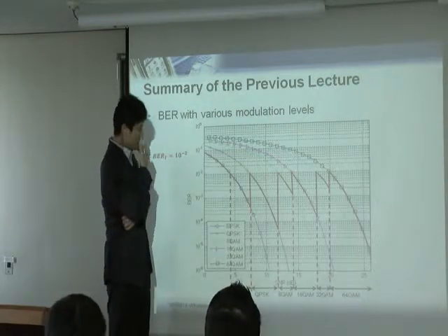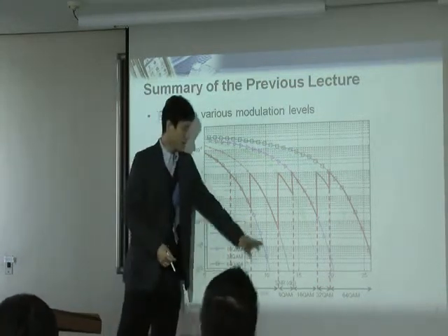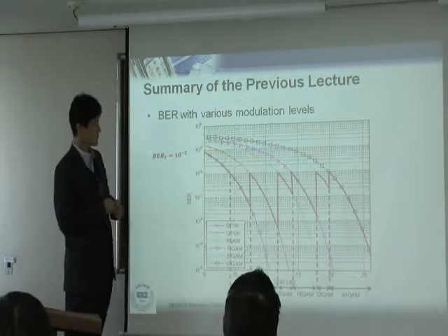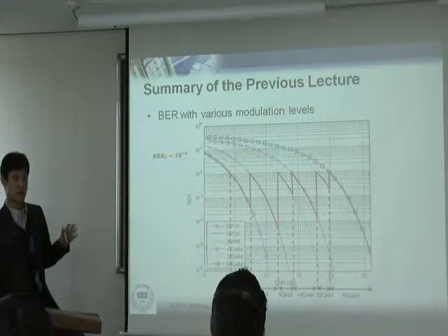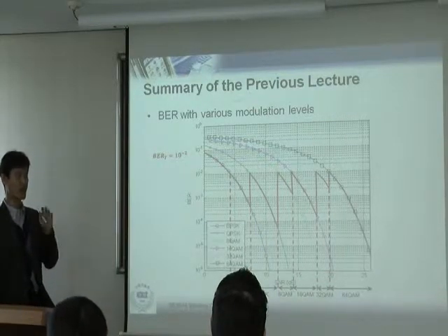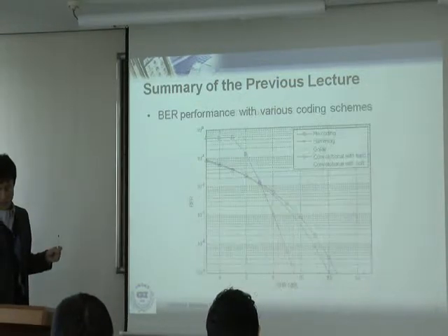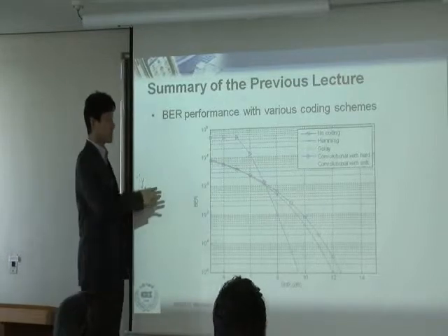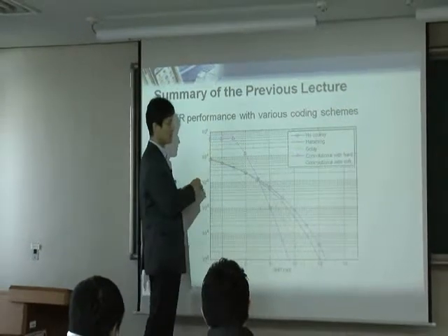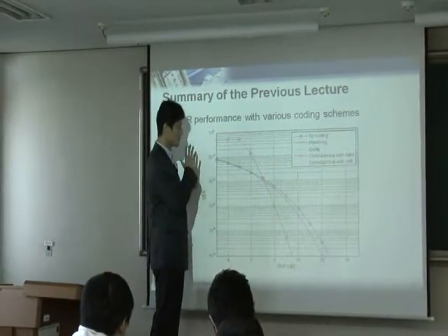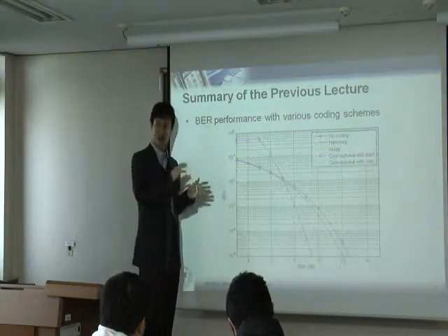So anyway, that's how you run the adaptive modulation, and that's how we determine the thresholds. And by the way, this is the case of no coding. We talked about modulation and coding, but in this case, we assume no coding, just the modulation. Now, let's think about only coding, no modulation. No modulation means that the modulation is BPSK. We are not changing the modulation. We just fix the modulation and change the coding.